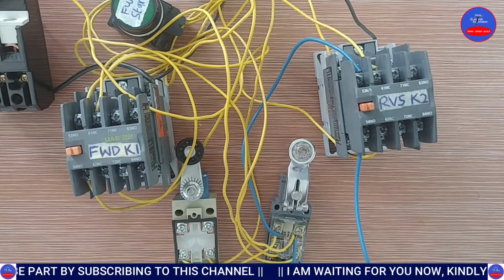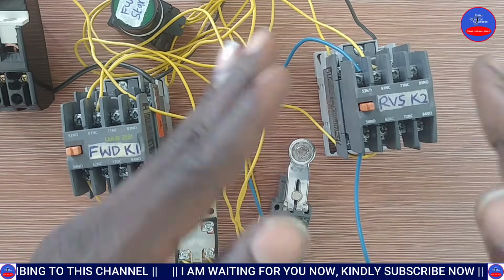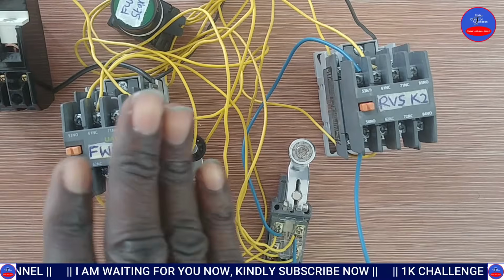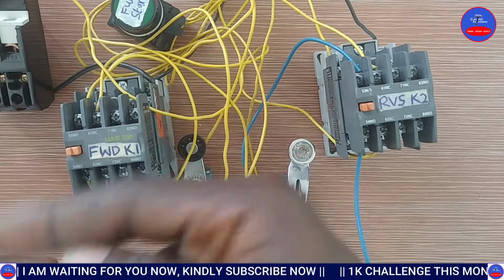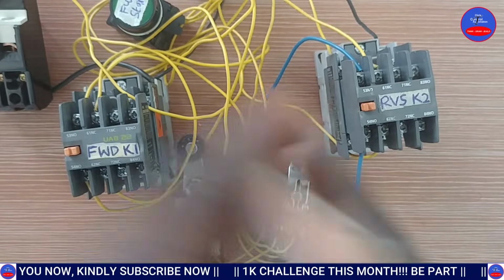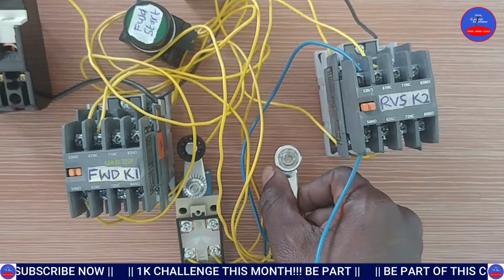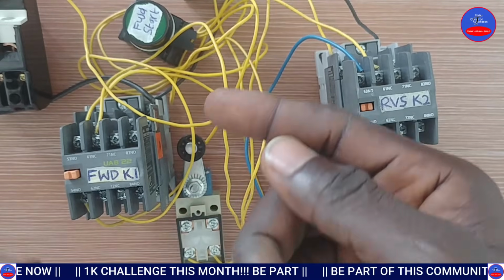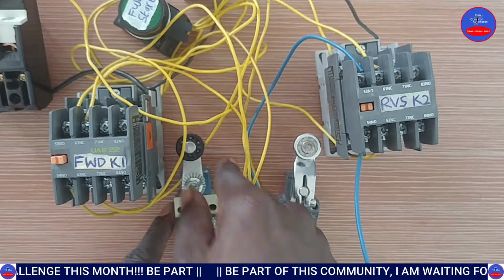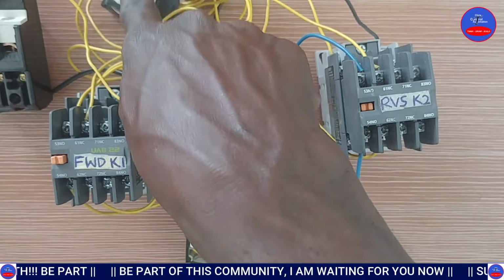When it gets to the destination, it will deliver. When it delivers its task, it will reverse back. When it comes back and hits limit switch 1, it will stop and wait for the next cycle. So it is not going forward and reverse on its own. When you press forward, it energizes. When you hit limit switch 2, it reverses its direction. When it hits limit switch 1, it will go off, but the forward direction will never start again unless you press the start push button.